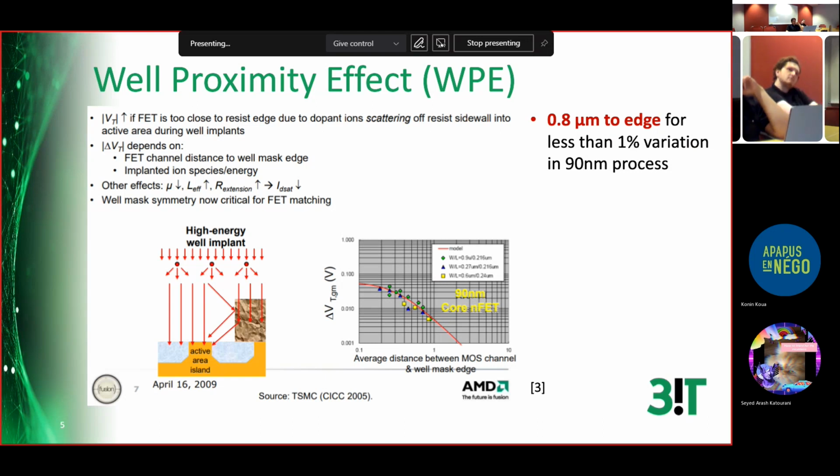So generally for the processes here and below, in my experience at Cadence, for all the projects that were working, the magic number was 1. We keep at least 1 micron to the edge for whatever device. Matching important or not, you need to have at least that.